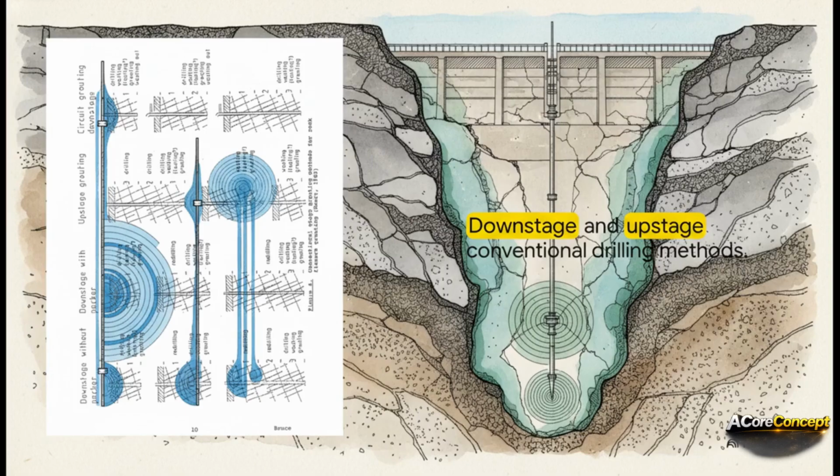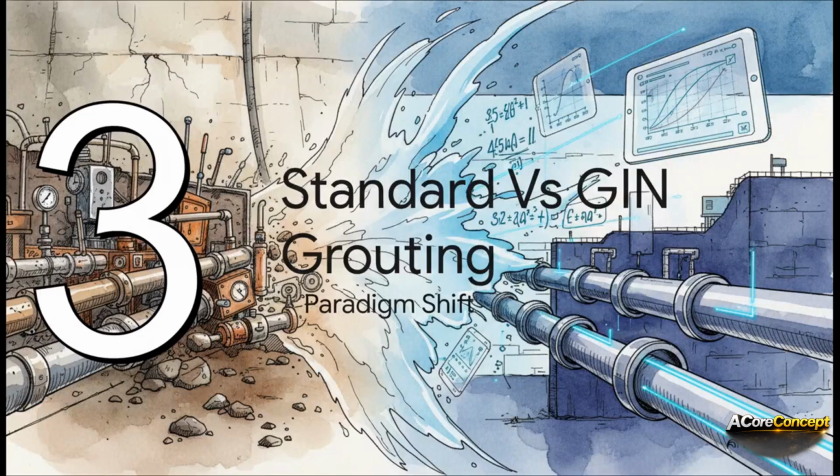Upstage drilling, on the other hand, means drilling the entire hole down to the final depth in one single pass. Engineers insert a packer at the bottom, grout that stage, and then systematically move the packer upwards. It's often faster, but it requires the uppermost rock to already be competent enough to handle those high pressures from below.